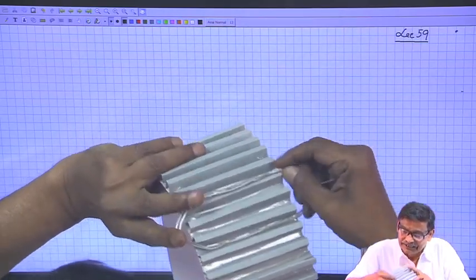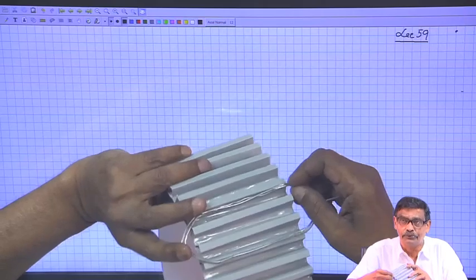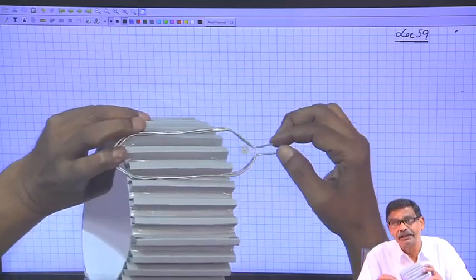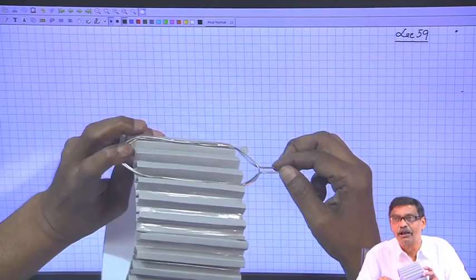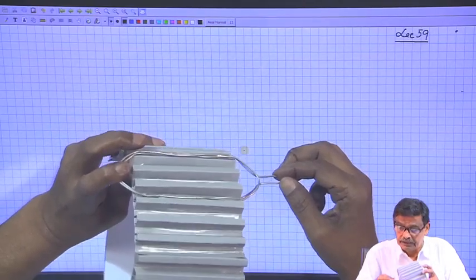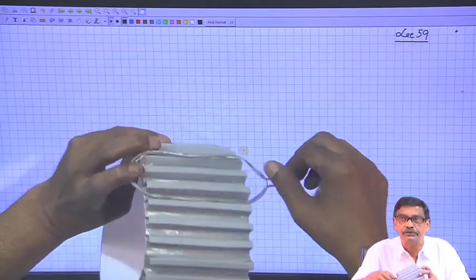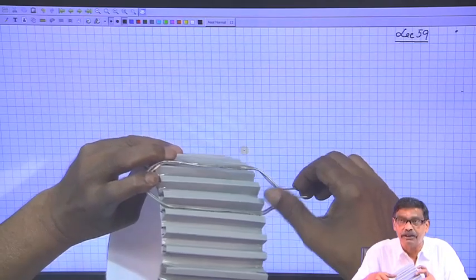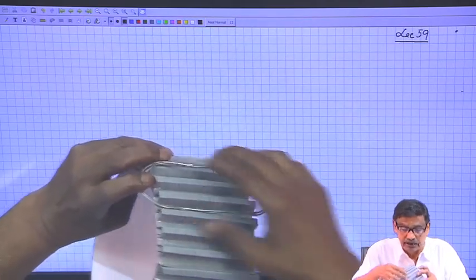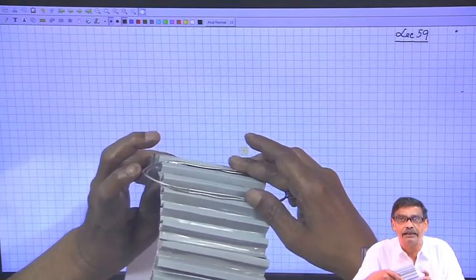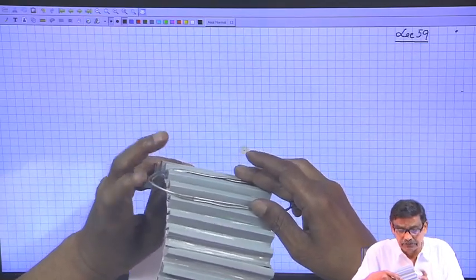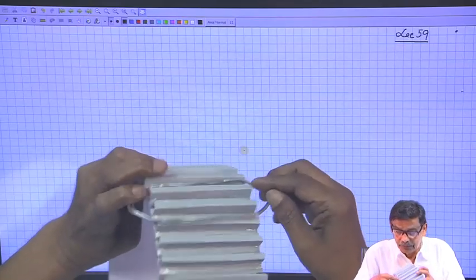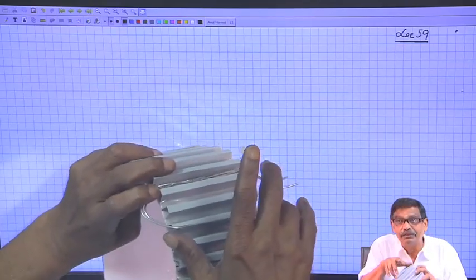Okay. That calculation will do, and it will have 2 terminals, that is what I want to tell. This is how the coils will be placed, and these are 2 coil sides. To make a coil, you require 2 coil sides, and these portions are the overhang portion of the coil. In this portion of the winding, there will be no induced voltage, because north and south will be all along the length of the machine.